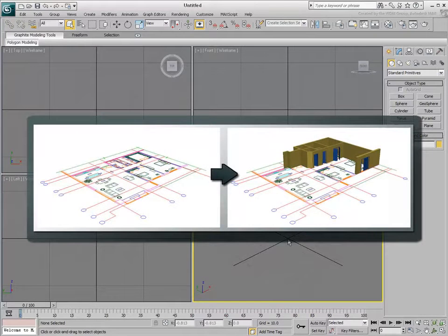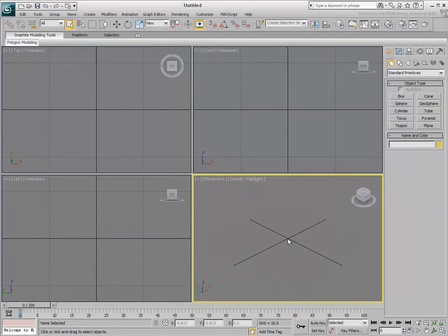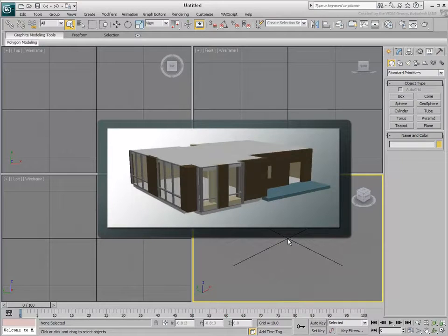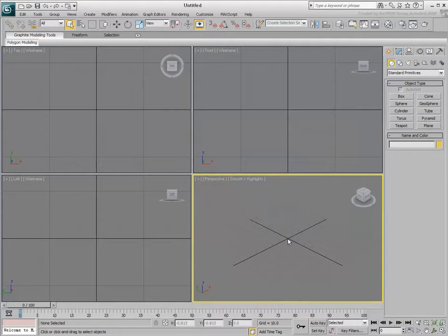One method is to use a 2D DWG file as a reference so you can build 3D geometry such as walls, doors, and windows in 3ds Max. The other is to use a 3D DWG file that already has 3D geometry, which you can embellish and render using the superior Max tools. Either way, the process of linking a DWG file remains the same.